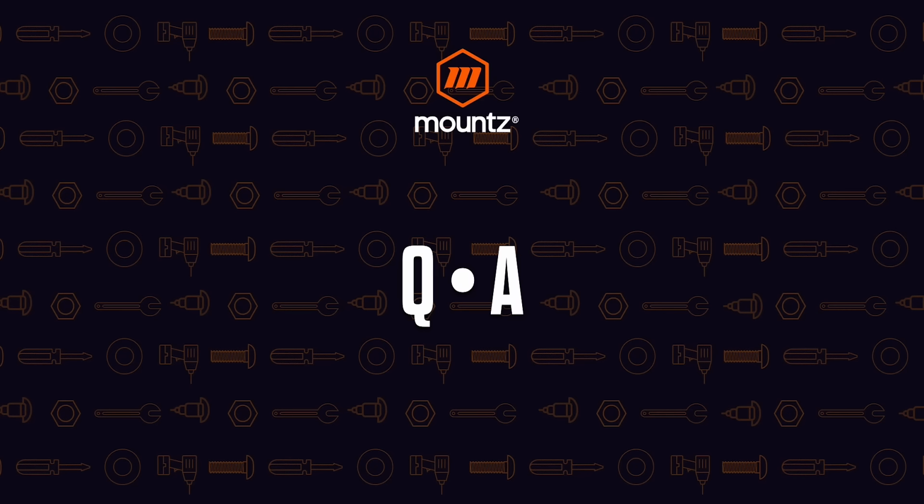All right, thanks, Dave. Next question was, how often does the wrench or screwdriver need to be recalibrated? So the ISO specification that we looked at, ISO 6789, says that it must maintain at least 5,000 cycles, and that whatever that particular value may work out for a specific application, you could track it that way.